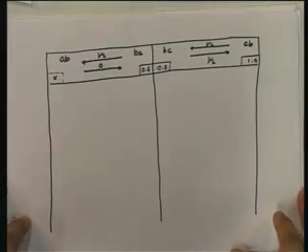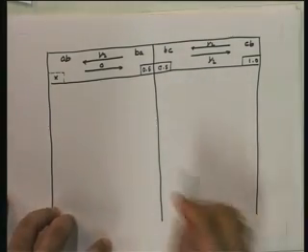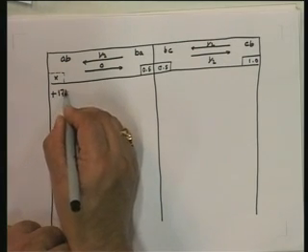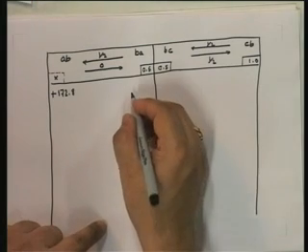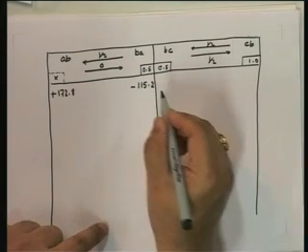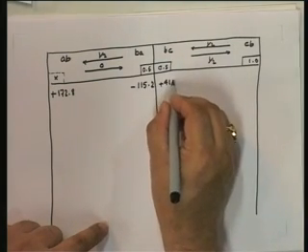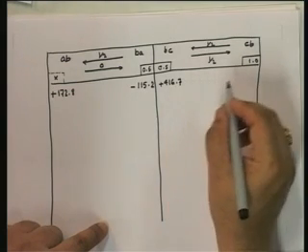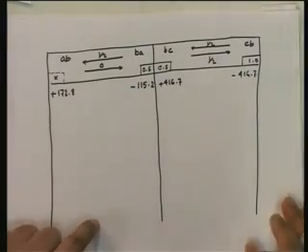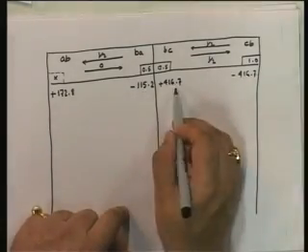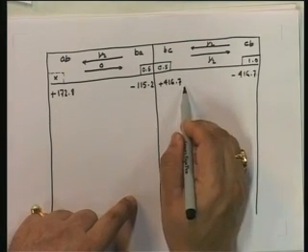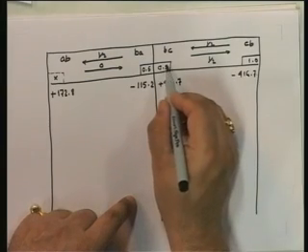So now let us start the procedure. The first step is writing down the fixed end moments. So this is plus 172.8. Then we have minus 115.2, plus 416.7, minus 416.7. So the first step is calculating the unbalanced moment here. What is the unbalanced moment over here? 301.5. So that one has to be distributed.